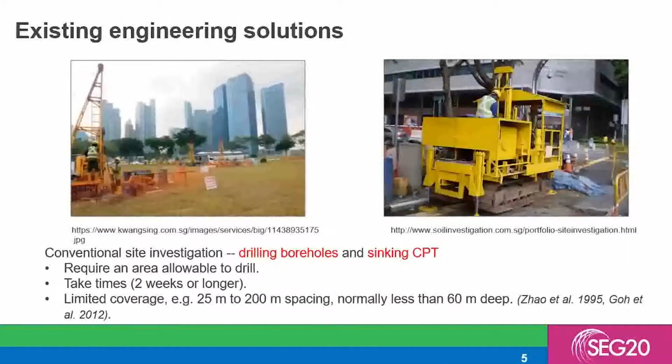The most conventional way of site investigation is drilling boreholes, just like the figure. Drilling into the formation and taking cores out, and then they will know the bedrock depths. The drawback is we can only get the formation structure at that particular point, and drilling itself is very time consuming and expensive.